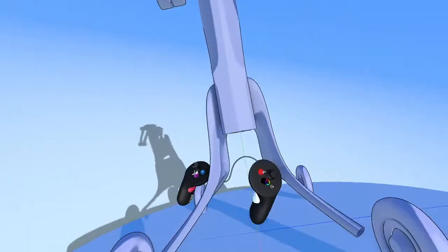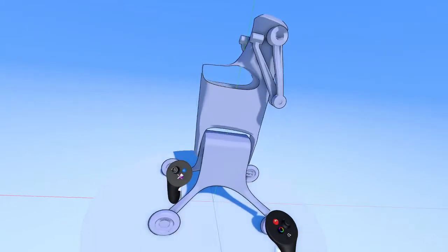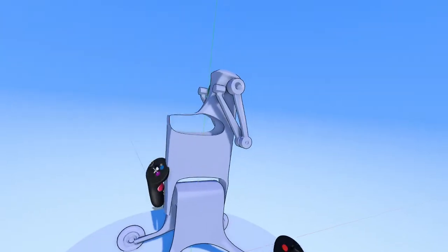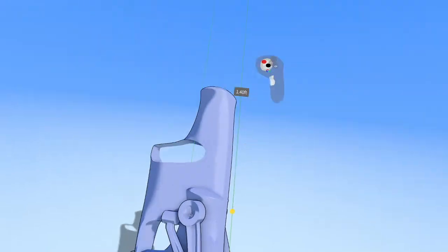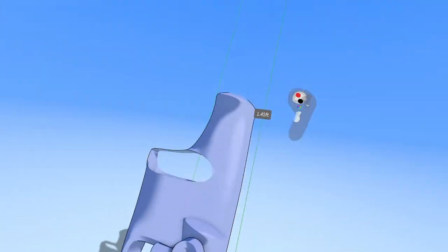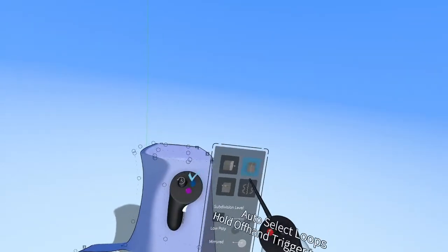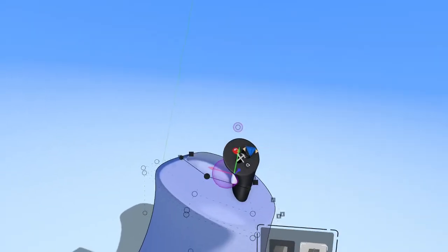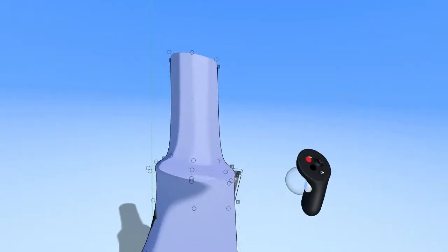Okay, as far as the legs go, you were right. I wanted to do that. I think we're going to come to that later. Or maybe we won't have time. But one thing I want to do is actually create the sensor housing up here. So what I'm going to do is actually duplicate up this shape. I know I want to use the original sub-D shape, but I want it to be separate from the rest of the original shape. So I'm going to turn on auto edge loops, duplicate up a surface like this, and